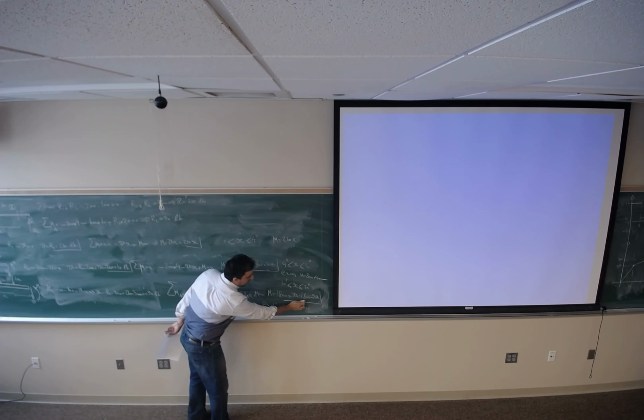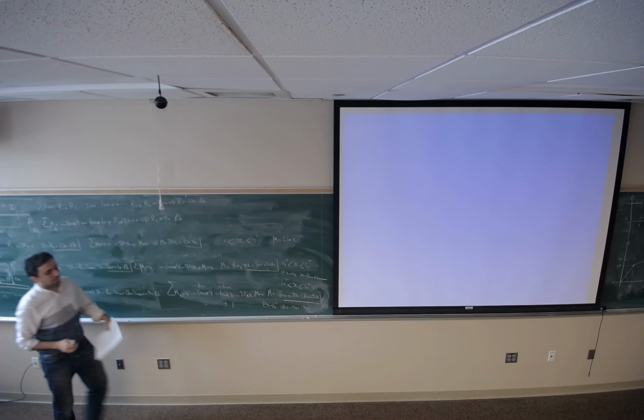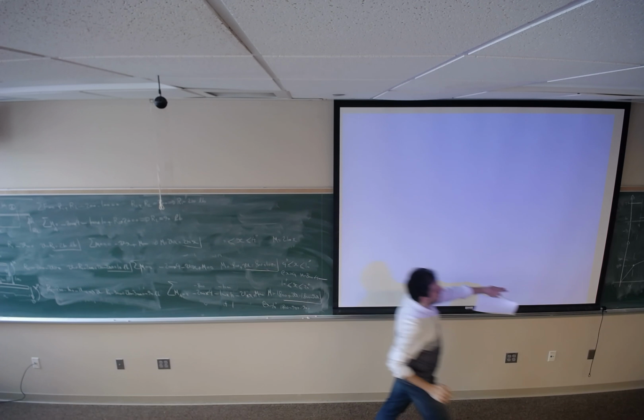And the last point, you should get 0 because at the ending point of the beam, it cannot support any bending moment. We can check. 1800 minus 90 times 20 is going to be 1800 minus 1800. So it's going to be 0. And this is how you can check your equation also.